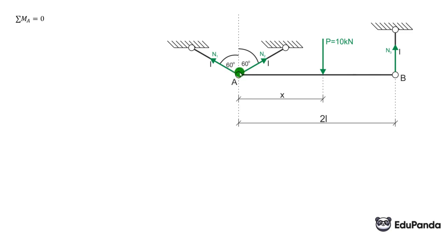It can be at point A. When we calculate the sum of moments at point A, N3 will be in the equation along with P. The force P times the arm x causes a clockwise rotation. I assume that clockwise moments are positive. When calculating reactions and forming the sum of moments, we either take clockwise as positive or counterclockwise as positive. We will get the same result regardless of how we assume, but we have to set something. I assume that clockwise moments are positive.